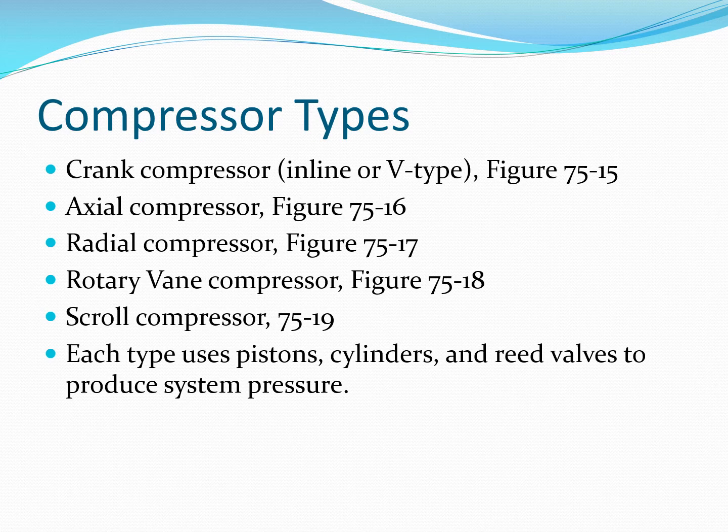I'm not really sure it's important for you to necessarily know how to take one apart or how to repair anything, mainly because if an air conditioner compressor fails, it's an R&R item. We just remove and replace the compressor. We don't bother rebuilding these. There was a time that we did that back in the 60s, 70s, and into the early 80s, but we've kind of gotten away from that. It's now a remove and replace item.